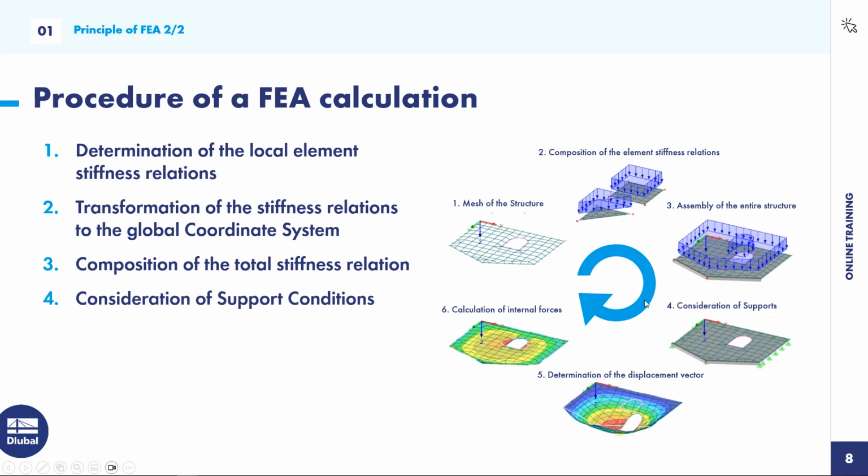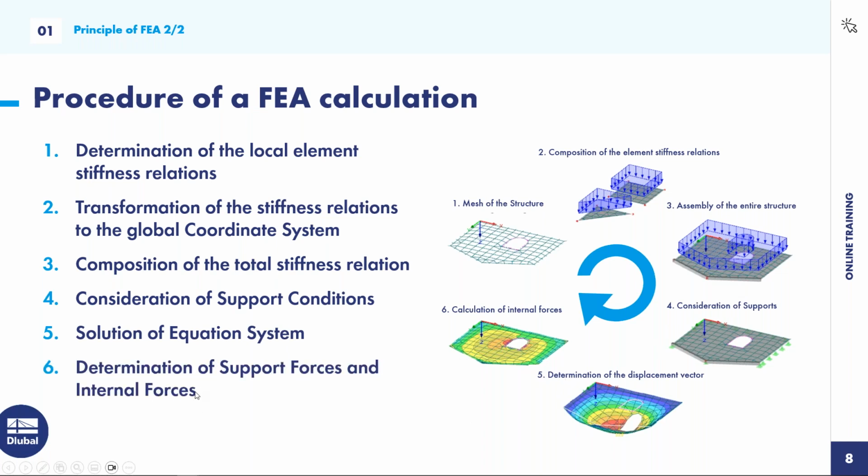And the next step, it's very important, you add your boundary conditions in form of supports or maybe external forces, so the computer can solve the system. And when the equation system is solved, you calculate, as I said before, the internal forces as part of the post-processing. So this was a very brief excursus.